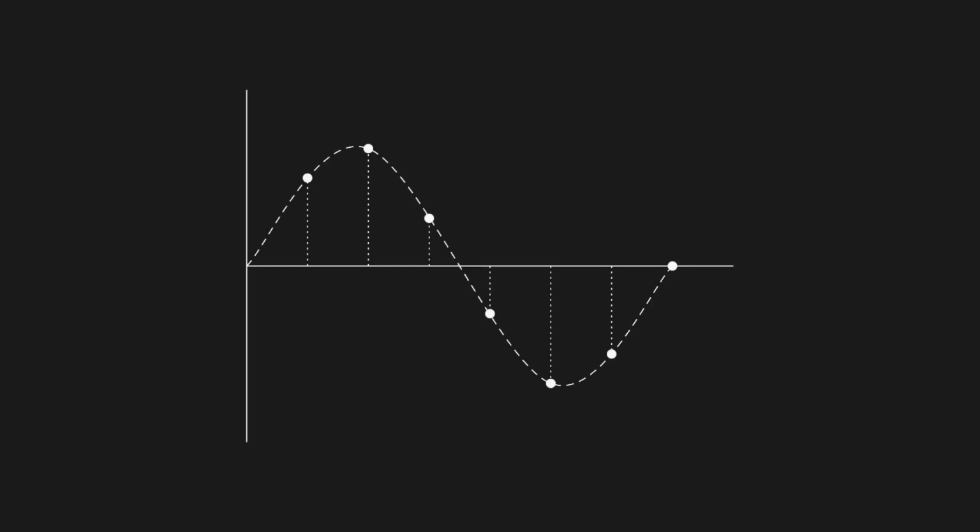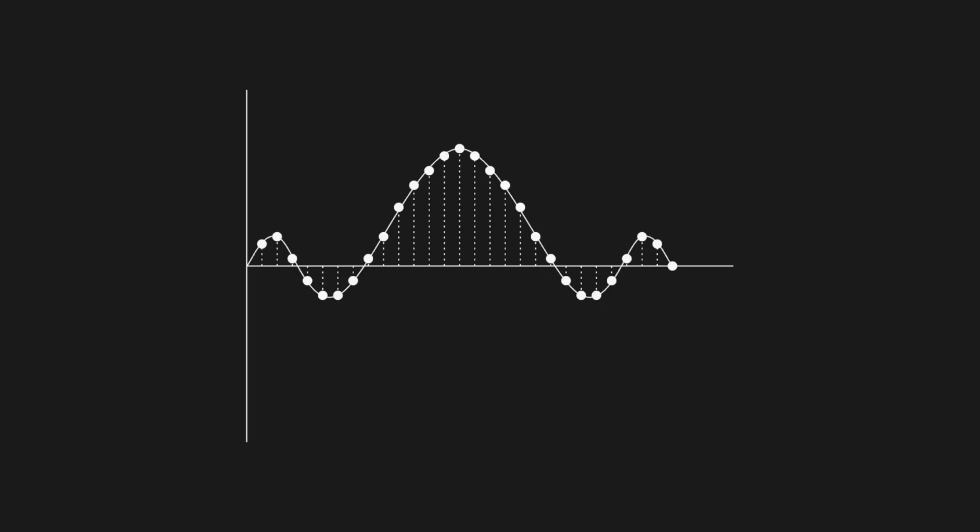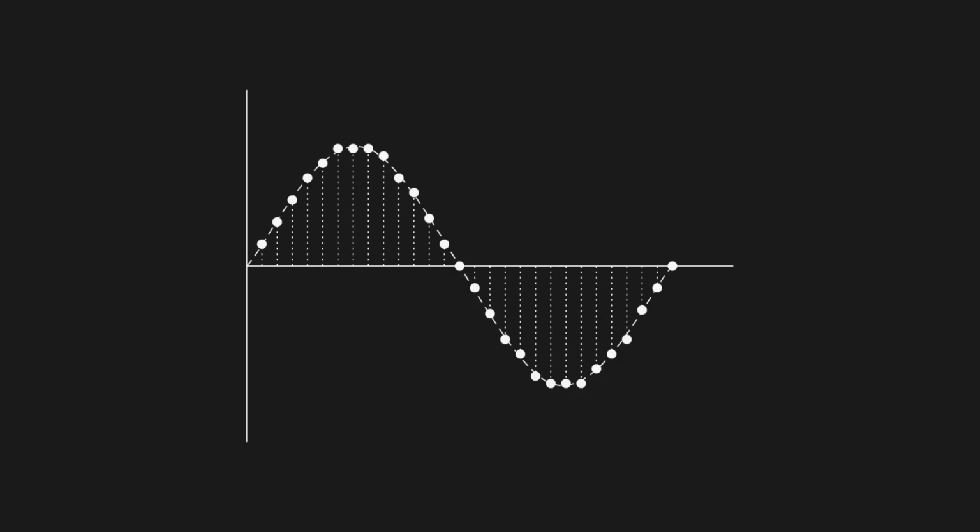An oversampling filter does two main things: resampling and interpolation. Resampling raises the sampling frequency by inserting zero samples between the originals, multiplying the sample rate by the interpolation ratio. Although the signal's spectrum stays the same, its sampling frequency increases. Interpolation then calculates the values of the missing points to create smoother transitions. For example, in quadruple sampling, the filter produces 4 samples for every original one.